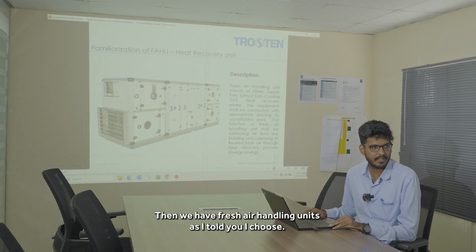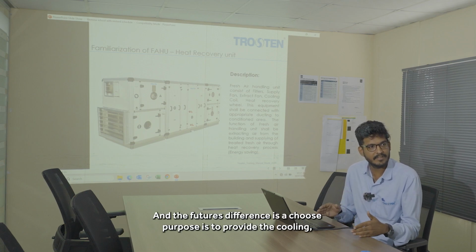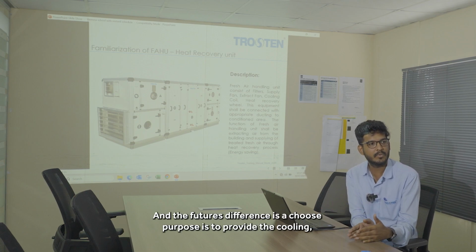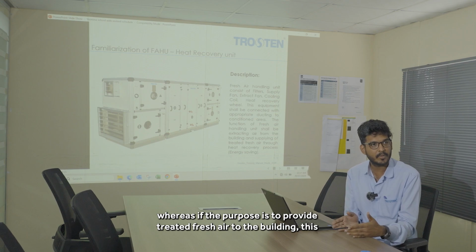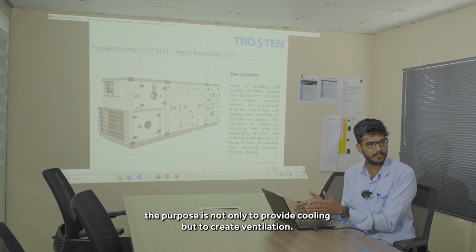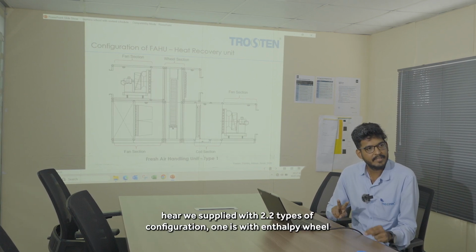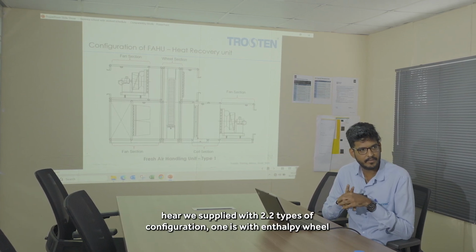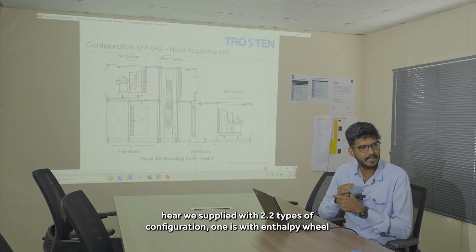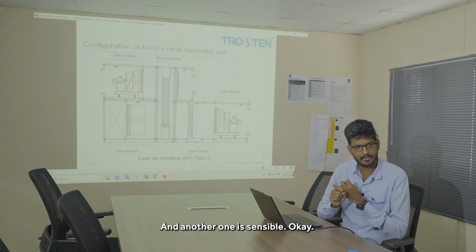Then we have fresh air handling units. The difference between AHUs and FAHUs is that the AHU's purpose is to provide cooling, whereas the FAHU's purpose is to provide treated fresh air to the building. The purpose is not only to provide cooling but to create ventilation. For FAHU, we supplied two types of configuration. One is with an enthalpy wheel and another is with 2 wheels, an enthalpy wheel and a sensible wheel.